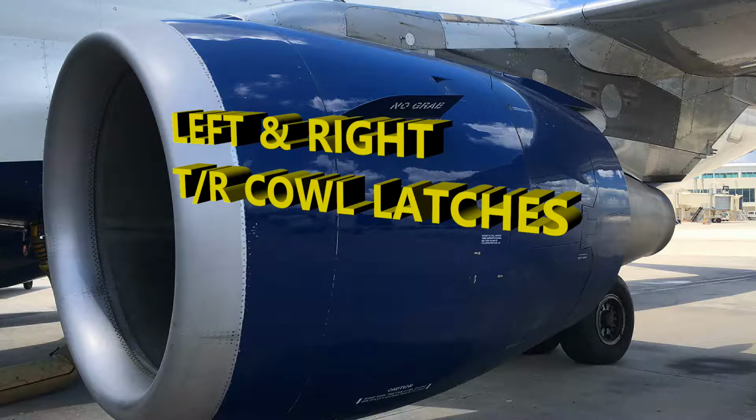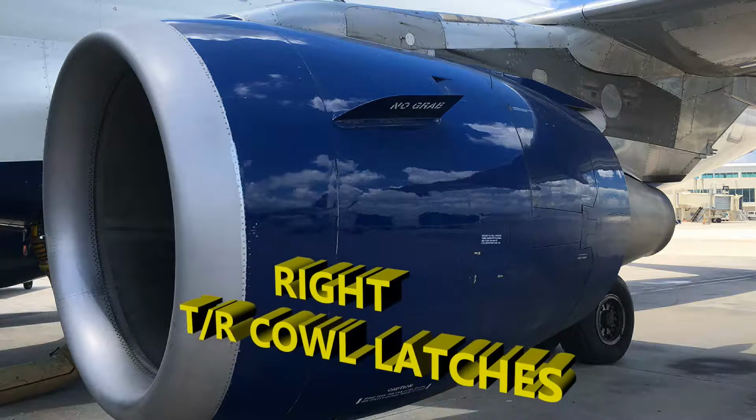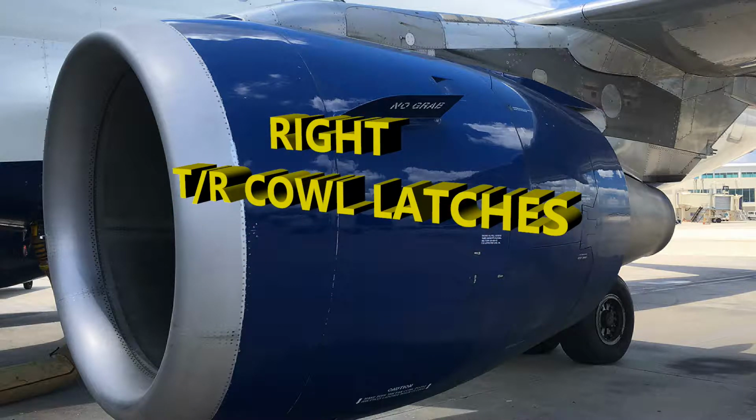All right. Now the right thrust reverser cowl latches and access panels. With the right thrust reverser cowl, you have L6 and L8 remote latches that have compression arms, and those are connected to the left thrust reverser cowls, okay, that come in contact with the remote latches. And you have 2 latch access panels here with the right thrust reverser cowl latch beam. And when it's in the open position, the latch access panel is going to give you access to latches 2 through 4 and the L6, L8 release handle.